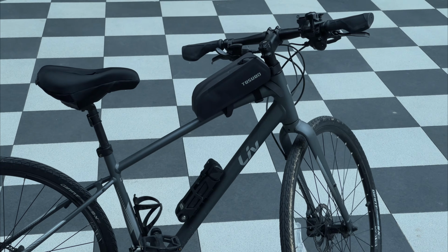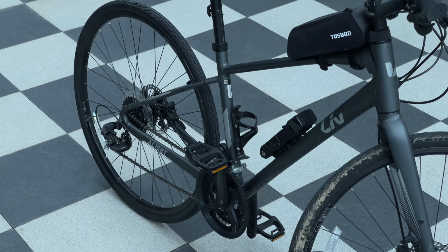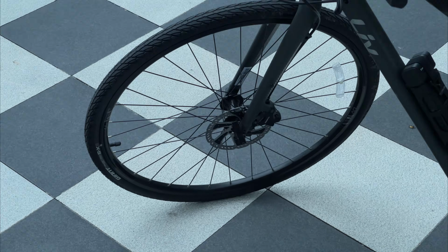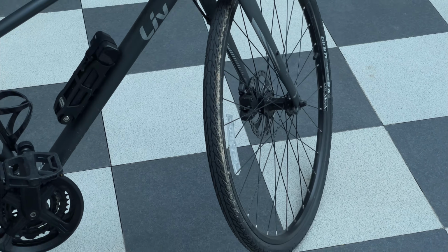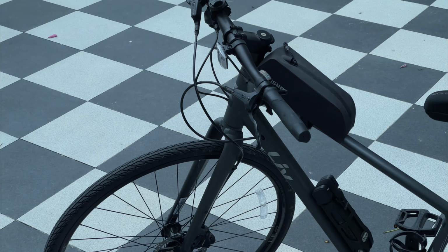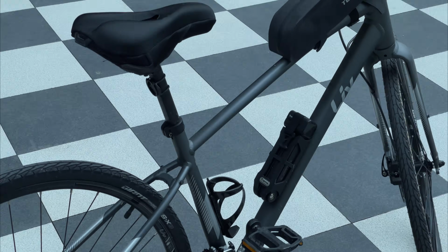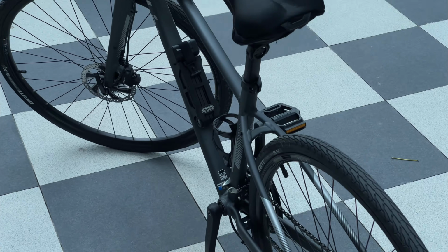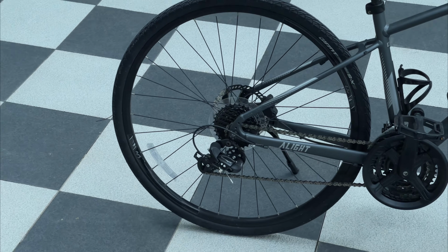This is the video used in this tutorial. It has not been sped up. The video only records frames at intervals. When shooting, try to keep the camera at an oblique, downward angle. Having too much background and sky enter the camera frame will make the final result messy and will also cause more computation to be spent on the background, which we do not care about.